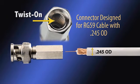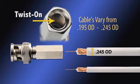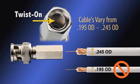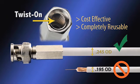However, today cable ODs range from 0.195 to 0.245, which calls into question the long-term viability of the connector. Because the thread is designed for a 0.245 cable, if the cable is 0.195, the connector will not tighten down properly. However, if the cable has the proper 0.245 inch OD, the Twiston connector can be a very cost-effective solution if terminated to the cable properly and is completely reusable.